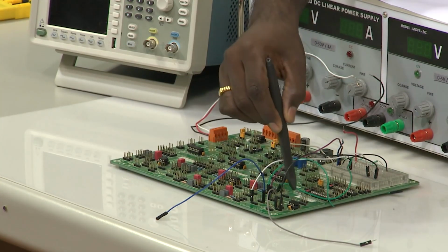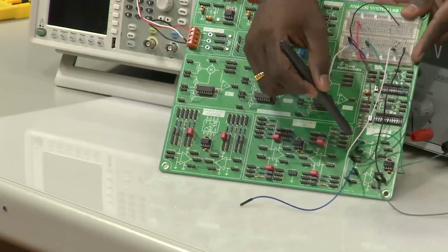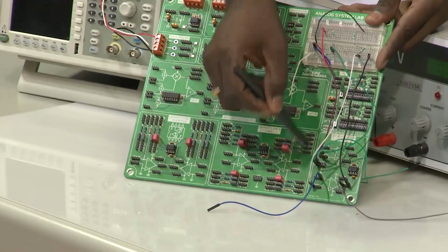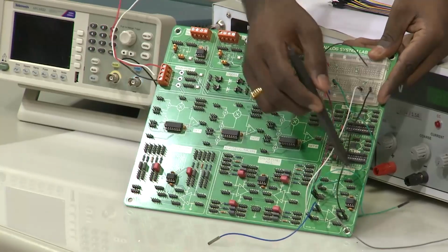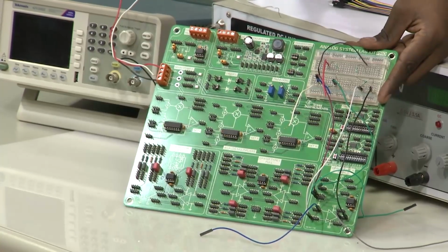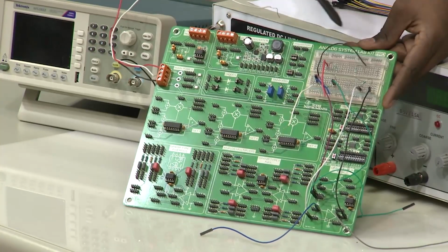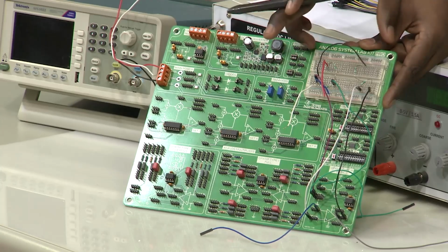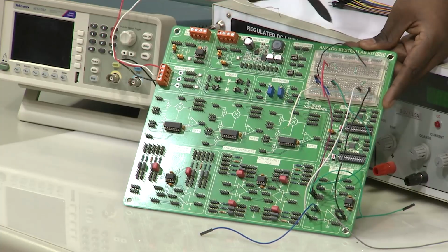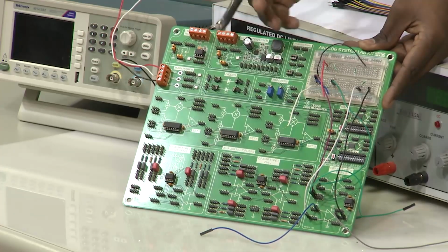When you observe here, one set of op amp is on the top side, and another set of op amp is on the bottom. Depending upon our experiment, we use either the top one or the bottom one. When you closely observe this board, in case you want to connect some external resistors or any other external component, the board also provides a smaller breadboard. It is similar to our regular breadboards, but smaller in size, so that any external components not available on the board, like resistors or other kinds of transistors, can be connected and wired through this using jumpers.